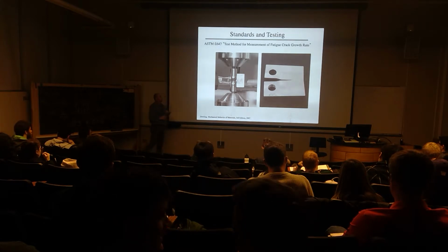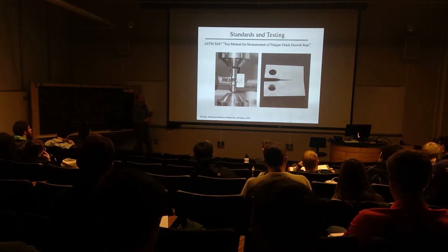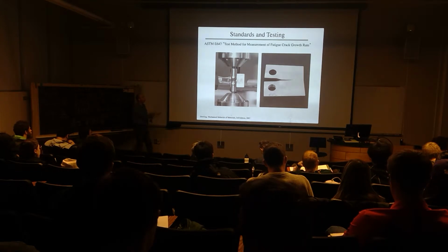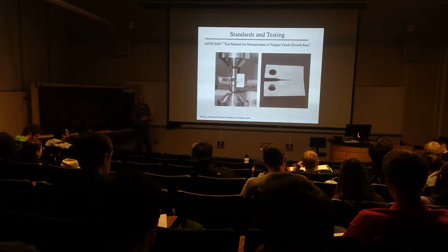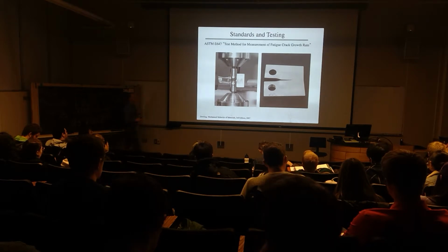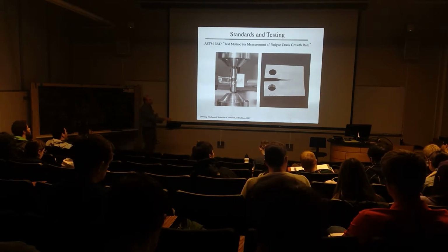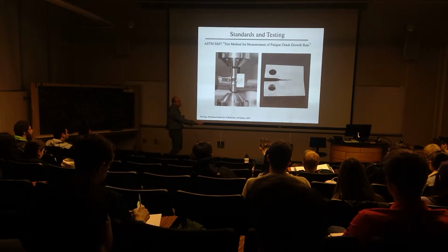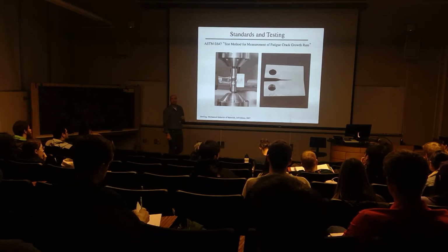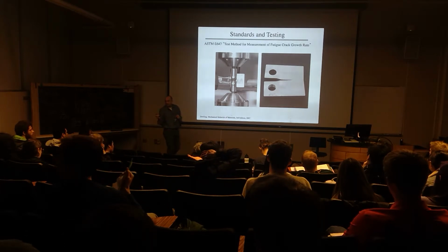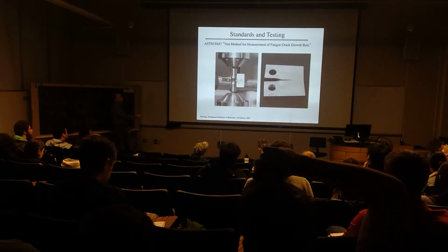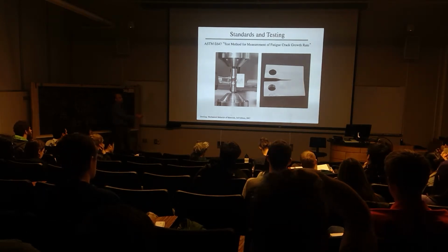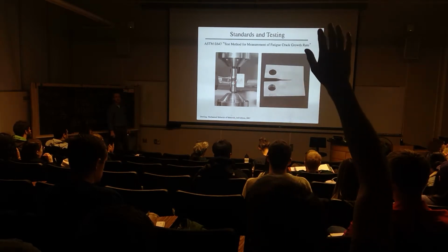So in order to do that, we're going to follow some guidance in terms of estimating fatigue crack growth rates. The most well-known standard is ASTM E647, which is defined as the test method for measurement of fatigue crack growth rates. Here's a good example. You can see from this cross-section, this is exactly that specimen that I showed you right here. That is that compact tension specimen geometry. It's used both for evaluating fracture toughness as well as looking at fatigue crack growth rates. And then what's done is we monitor the incremental rate of cyclic crack extension that develops in that particular material as a result of the conditions of loading.